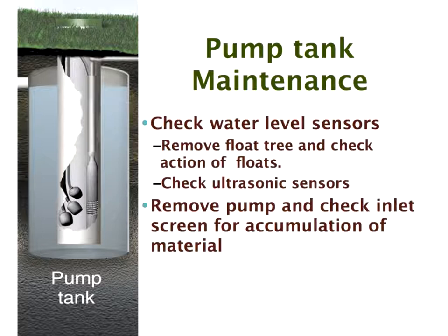Check the water level sensors. These are the floats, or if you've got some other type of water level sensor. Check the action of the floats. If you have an ultrasonic sensor, check it.